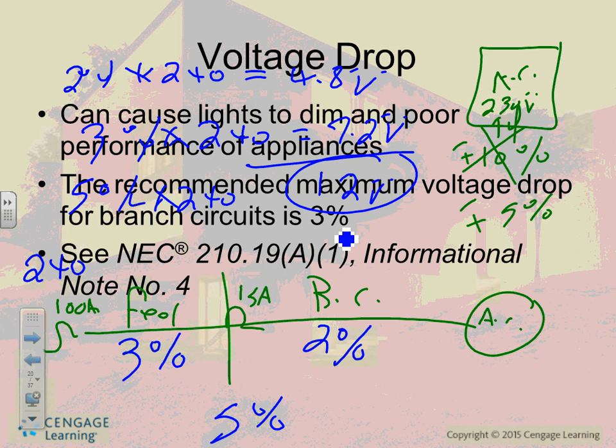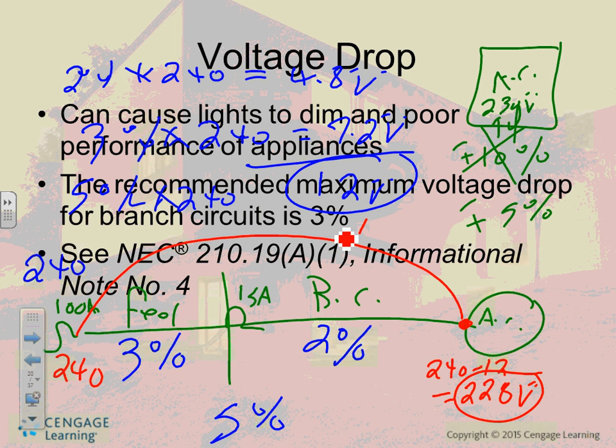Look what happened. I started with the voltage here, 240. By the time I reached this, I lost 12 volts. So that will be 240 minus 12 is what, gentlemen? 228 volts. So I can drop down to 228 and my equipment should function okay. You can see what the voltage drop is. What happened to the 12 volts? The 12 volts got dropped where? Here's my 12 volts, in both the branch circuits and the feeders.